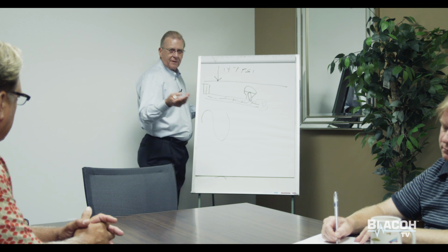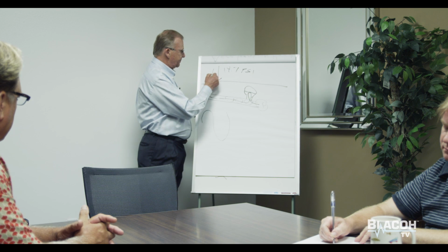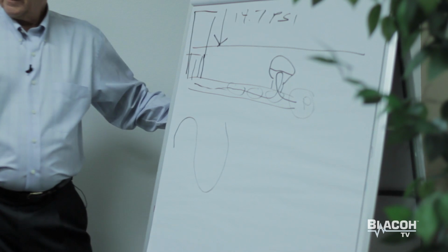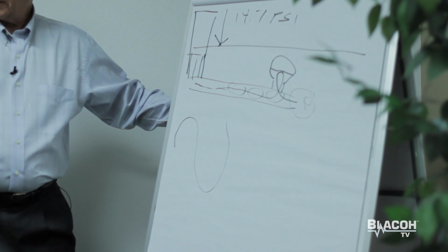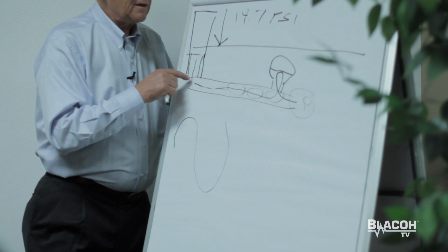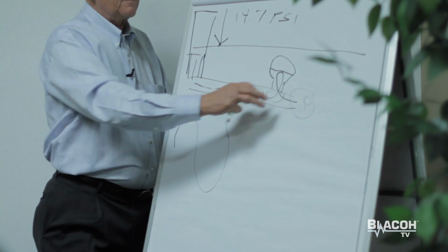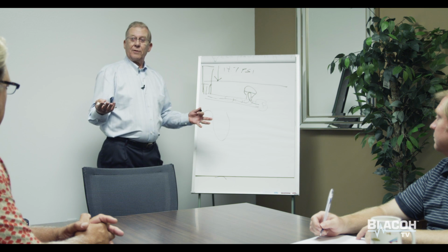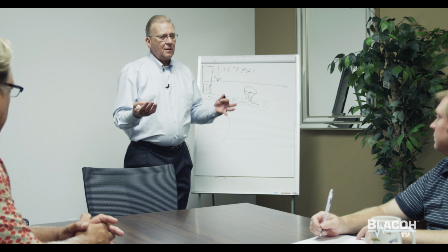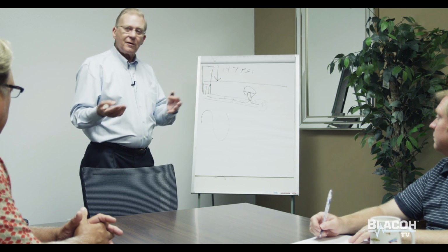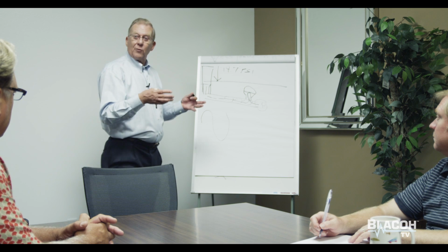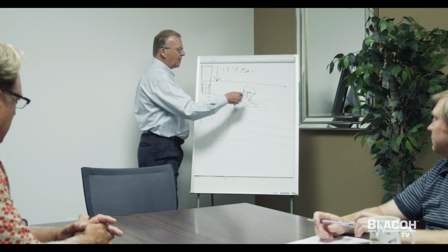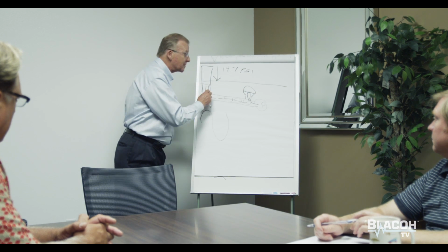Now, another scenario that can happen is that we have too much positive pressure going to the pump, okay? Because of the acceleration head and the pressure involved, when the valve closes, we create water hammer. And all water hammer is a change in velocity or a change in acceleration, typically rapidly, okay? And that occurs when this valve ball closes, but the product is moving because there's acceleration.